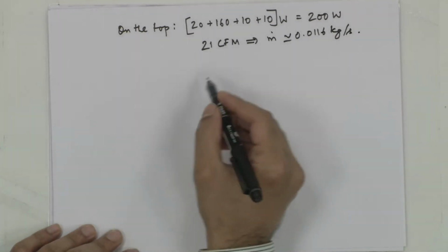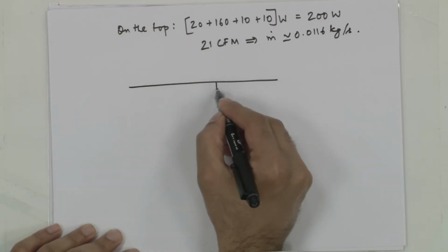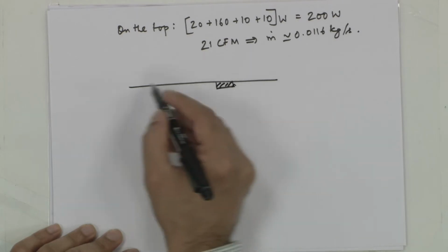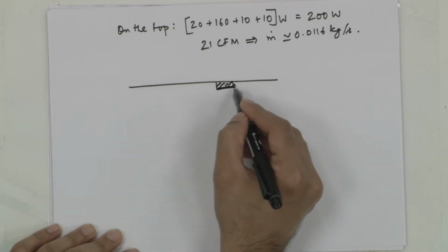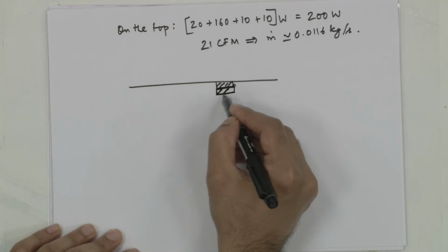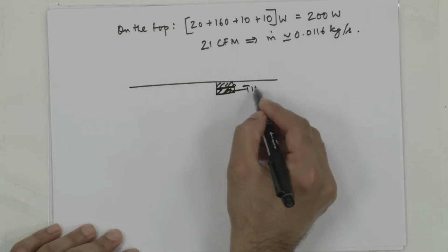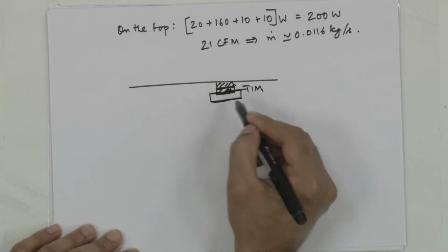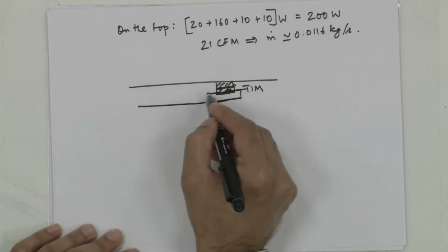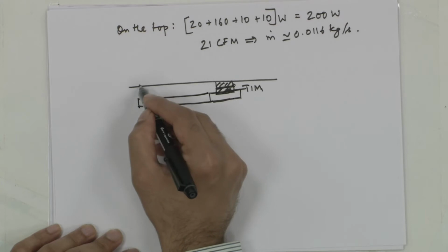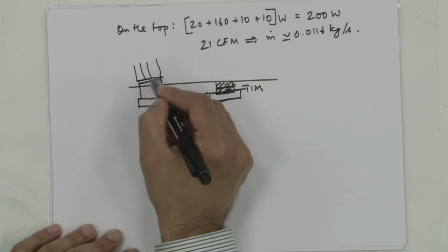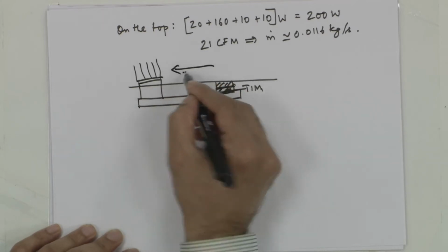And this is the bottom side of the structure. So, the heat source is here. The heat source on the bottom side is bridged to a copper plate through a thermal interface material, and then it spreads over a larger copper plate, and from here there is another plate, and then the heat sink is mounted where air is flowing.